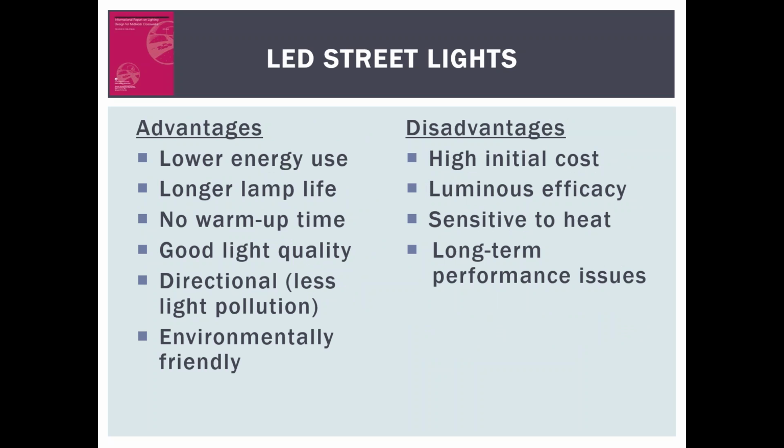LED, of course, stands for light emitting diodes. Many agencies are exploring or are just converting to the use of LED lights due to the very low power use, the longer life, the lack of a warm-up time, as they come on almost instantaneously, and the good color quality. Concerns with LED lights were the high initial cost of the lamp, and having a proper lamp design to eliminate heat buildup. Other issues that did exist were the amount of light that can be provided from an LED light source, or the luminous efficacy. LED technology is changing and improving rapidly, and the costs are coming way down.